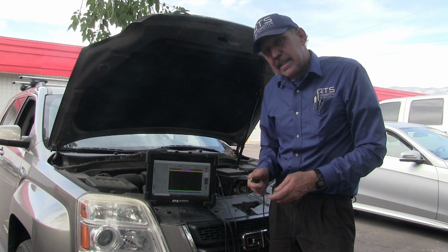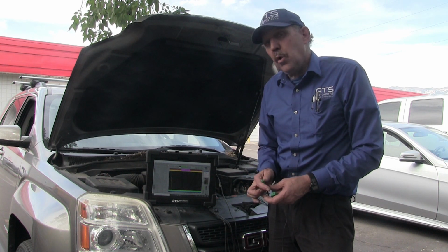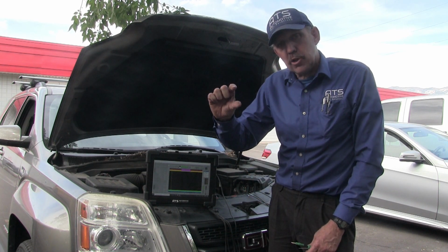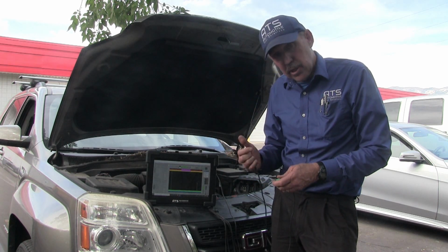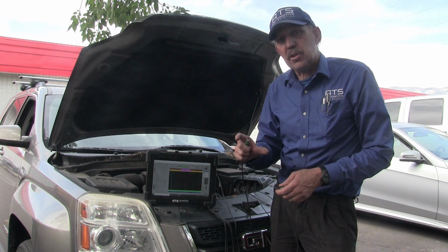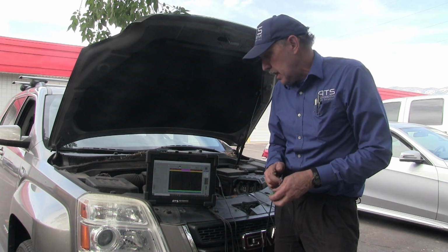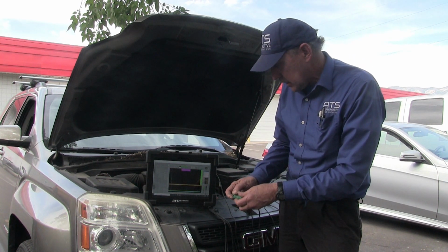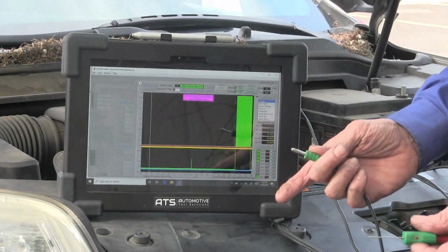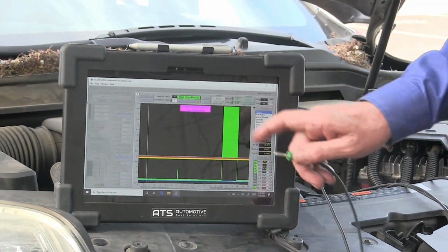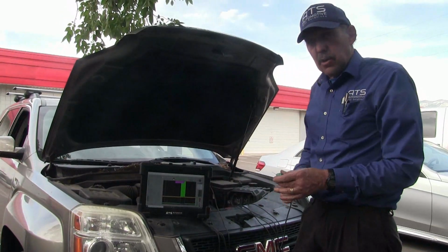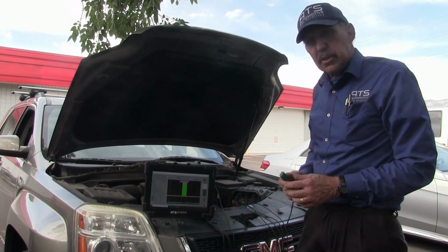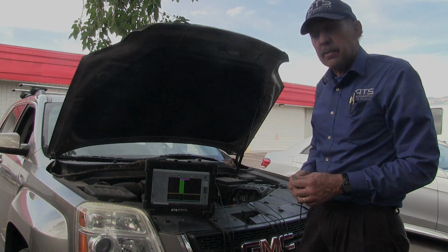Either of those have greater than 1 million ohms. So if I connected into this wire, I wouldn't expect very much voltage drop. When I connect this into this type of a signal for the O2, I should have really close to 5 volts present. Again, if I connect that, I can see the voltage, and when I disconnect it, I don't. That's 5 volts amplitude. So now let's go ahead and connect this to the circuit and watch the scope.